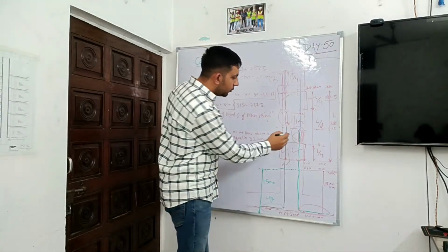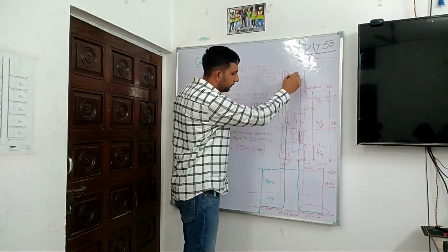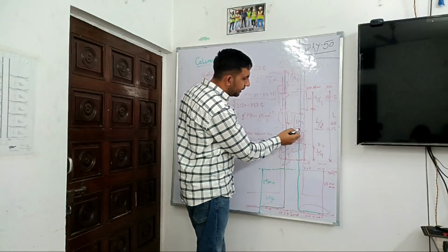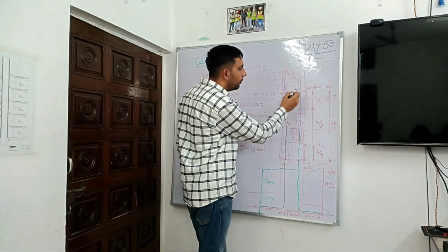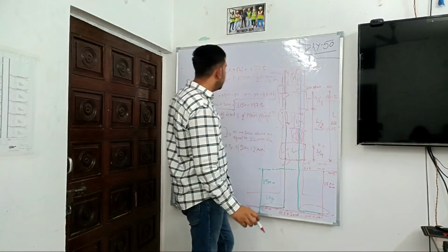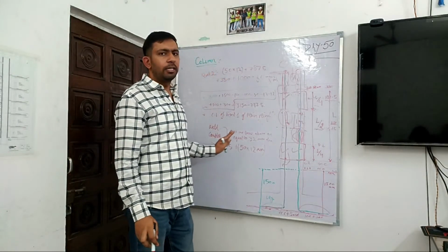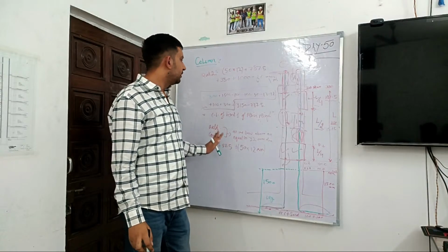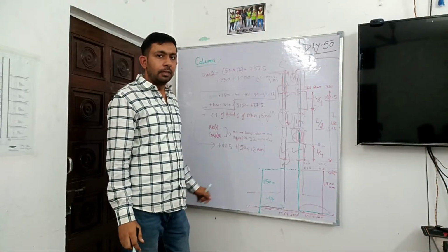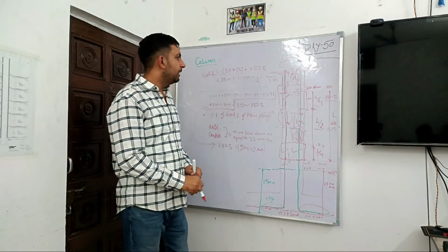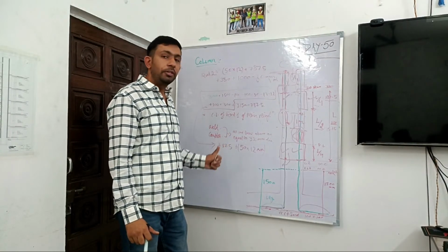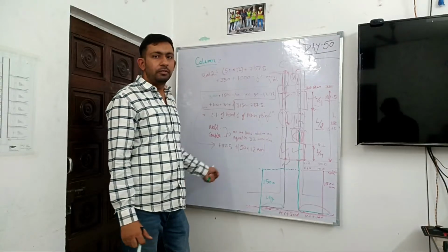This will give us the value of rod 2. In the same way, we can also calculate the value of rod 2 dash. In this case, we will consider 50D, then this distance, plus L by 4, plus slab beam height, plus 1 meter, minus cover. In this way, we can easily calculate as many bars as are given in the column section of our project. In the structural drawings, we have to read carefully all dimensions, all covers and all detailing. So I hope this is clear to you all.